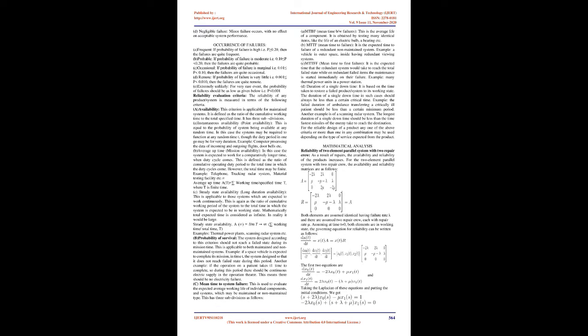Accumulations of dirt etc. may cause electric failure. 4. Evaporation. Filaments age because filament molecules evaporate. 5. Fatigue. Prolonged repetitive loading may cause fatigue fracture. 6. Friction. This commonly produces failure in belts, gears, and machinery in general. 7. Temperature variation. Repeated expansion and contraction would weaken the material.